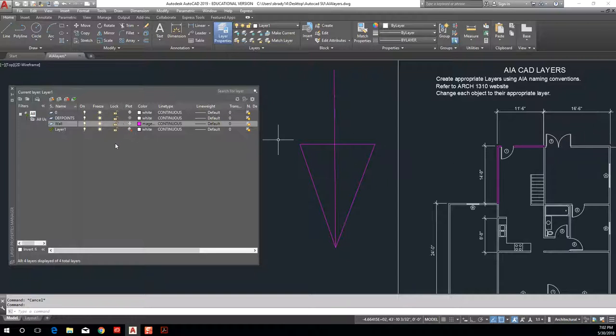All right, so when I say layers organize drawings, I mean that I assign architectural elements that are similar in nature, walls, doors, windows, to a layer with that name. So the wall layer, I put the walls on that layer, okay? So that's the organizational part.